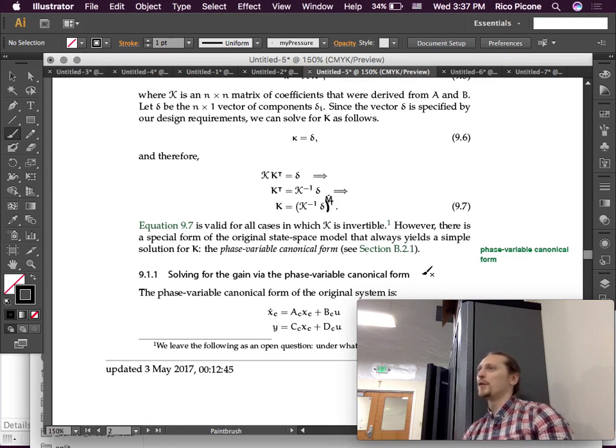And the realization form, like phase variable canonical form, which is the typical one, is just a bunch of derivatives of one of the terms. So you might end up with the fourth or fifth derivative of the position as a state variable, which isn't super enlightening. You could plot it, but it might look really weird, and you wouldn't have any physical intuition for it.